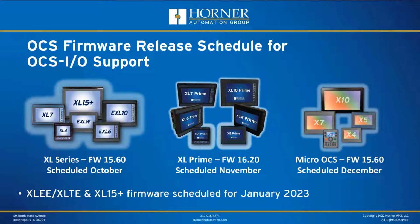That was from Sandor, because on our micro series OCS, which is our entry-level product, when we added RTD PT100 support to that product, we did it in an economical way to avoid cost being a problem, because that's a very cost sensitive product. But with the micro OCS, I believe it's limited to something like minus 50 to plus 200 C. So that is a product that does have limited temperature range, but that's not the case with OCS-IO that supports the full range.